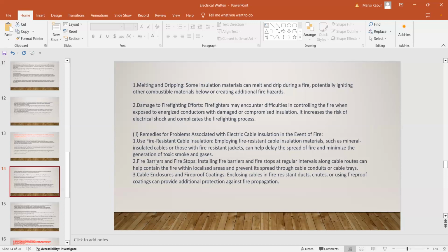If suppose your cables are penetrating out of the engine room, there are approved electrical putties, right? So that fire is not going to another compartment, correct? Guys, we have different kinds of bulkheads on board the ship. Class A, class B, correct? Yes, sir. So suppose you have to pass an electrical wire through the class A bulkhead. Can you just drill and pass? These gland packings and all, it's needed. Everything is there.